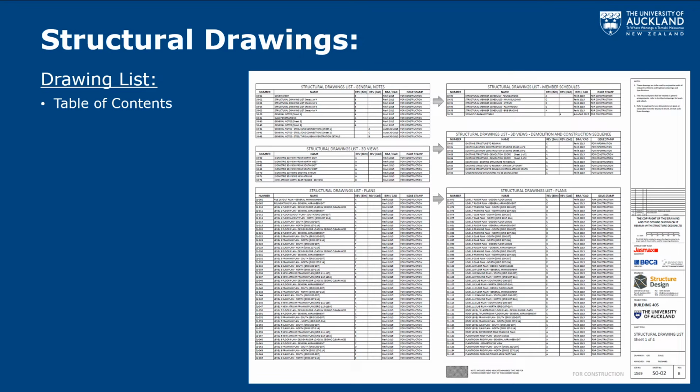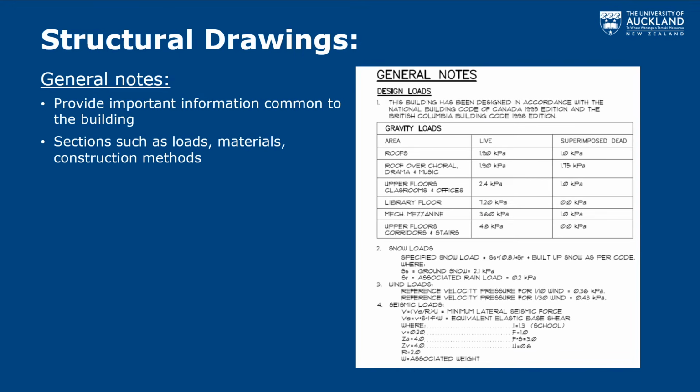And then it also has what was the current issue, so this set of drawings is what has been issued for construction. It would be expected there would be yet another set of drawings which would be as-built, so after the building has been constructed, just to confirm that what was specified actually got put in the same place as intended.